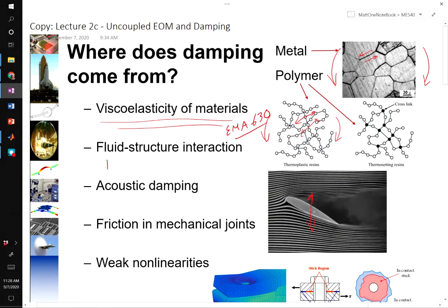And an important thing to notice here is that damping can be positive or negative. So we can get damping, or we can actually get energy pumped into the system that can cause the vibration amplitude to increase with time and eventually even cause the wings to break. So that can be dangerous, and that's something that's important to think about if you have things like an airplane or a light structure in the air, or underwater structures.